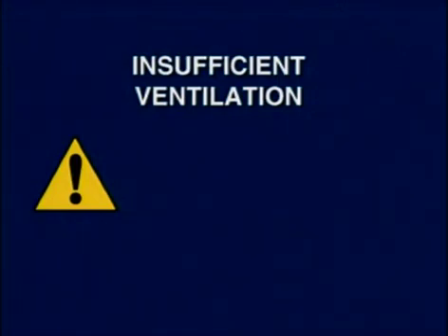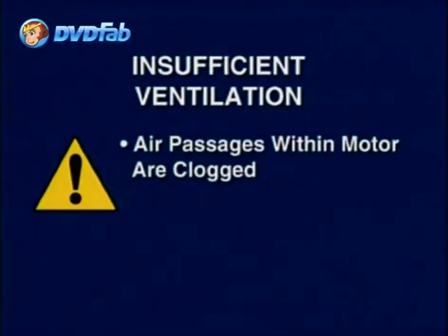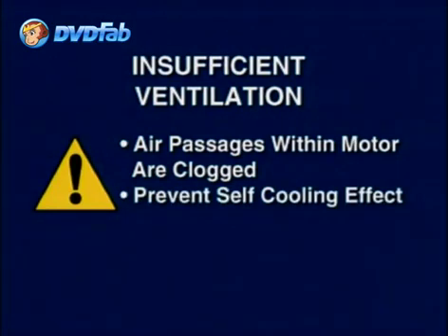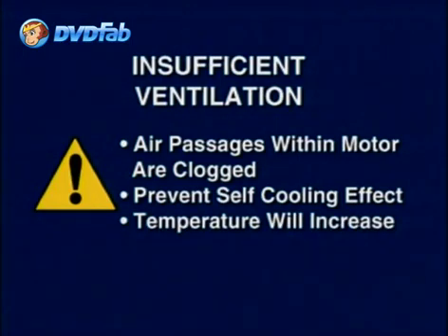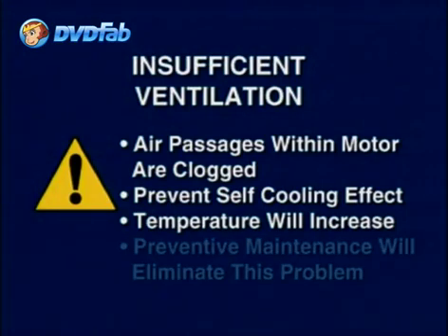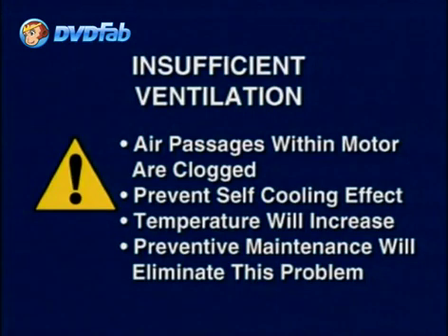Insufficient ventilation can occur to a motor when the air passages within the motor are clogged with dirt or other material and prevent or block the natural cooling effect of the motor. The motor under these conditions can reach high temperatures without increases in current, which means that it can go undetected until it is too late and burn out. This should be an extremely rare problem if proper preventive maintenance is performed.